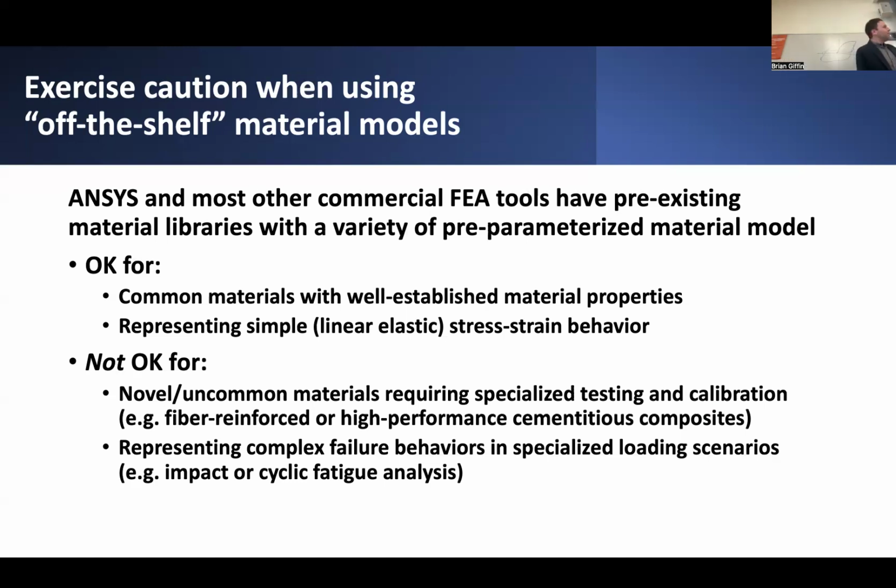But in general, if you are trying to really emphasize the use of nonlinear material behavior, if that's core to the problem that you're trying to address, then you should really be the one to determine what's the appropriate model to use, how has it been validated, and do I need to do some additional validation against experimental data that I've collected in order to parameterize my own model? So do give some time and thought to that, because I think that's going to be really critical, not just for your project, but in general, as you go out in practice and try to use these tools.